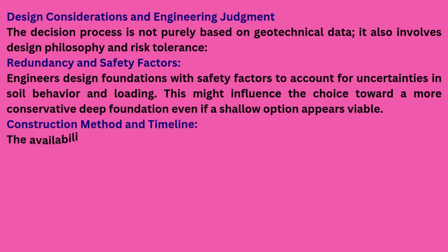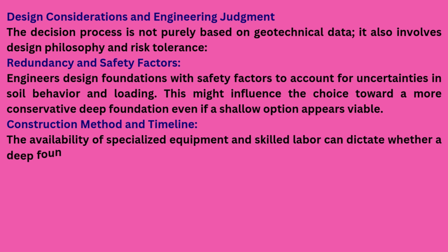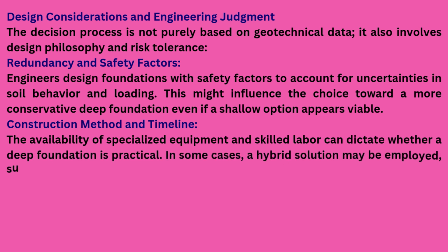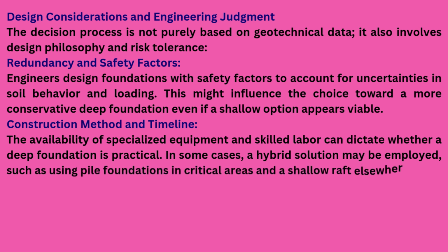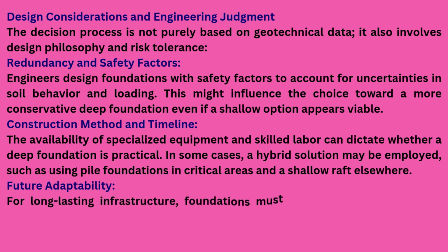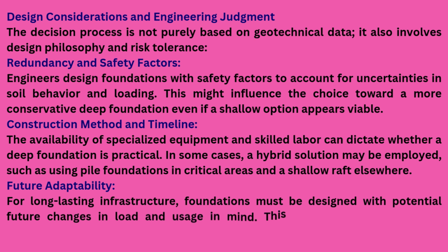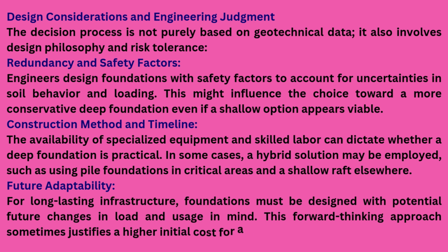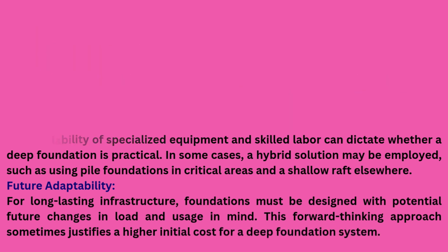Construction method and timeline. The availability of specialized equipment and skilled labor can dictate whether a deep foundation is practical. In some cases, a hybrid solution may be employed, such as using pile foundations in critical areas and a shallow raft elsewhere. Future adaptability. For long-lasting infrastructure, foundations must be designed with potential future changes in load and usage in mind. This forward-thinking approach sometimes justifies a higher initial cost for a deep foundation system.